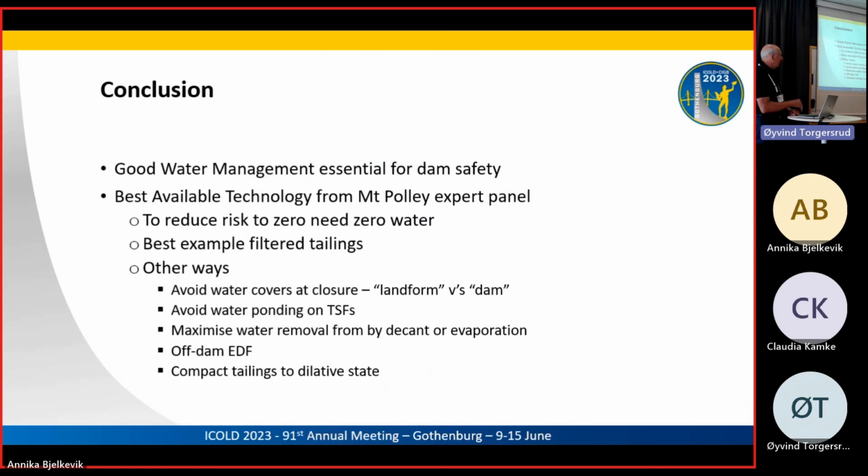So we've got to think pretty carefully about what our water management is going to be. Try to avoid as much water on TSFs as we can, try to maximise removal, maybe consider off-dam environmental storage, and ideally if we could compact our dams, the better off we'll be.